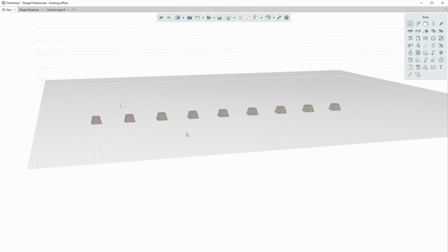To insert the assembly into the model, select the assembly tool and specify the following parameters. Assembly position relative to axis. Each option on the drop-down list shows how the bounding box of the assembly will be located relative to the insertion point on the levels plan or 3D view. Assembly horizontal offset, or x-axis offset, relative to the insertion point of the assembly. Assembly vertical offset, or y-axis offset, relative to the insertion point of the assembly. Assembly style. Rotation angles.